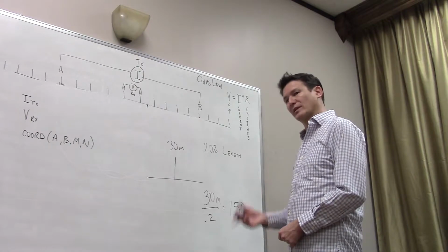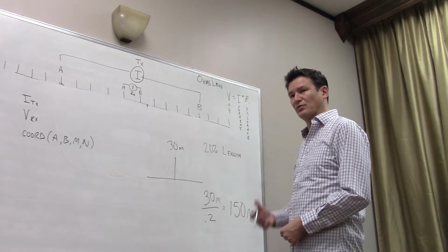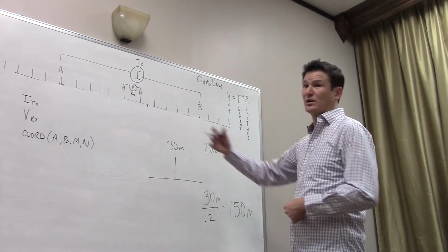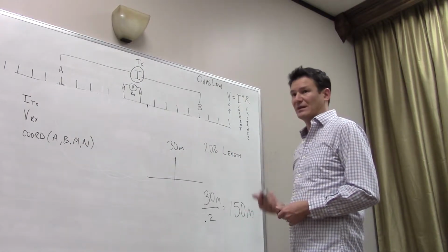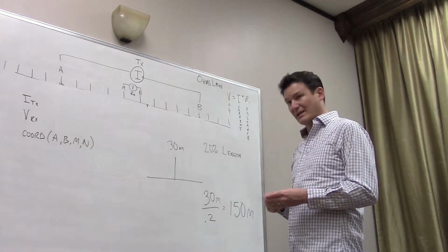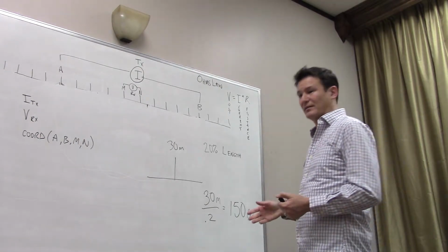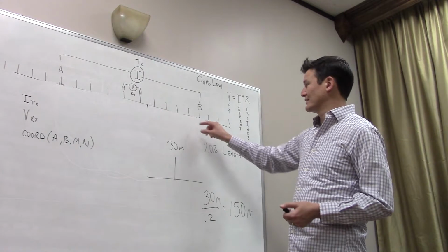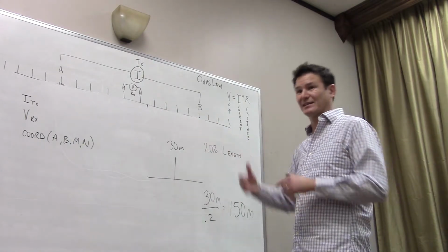Now our systems are 28 electrode, 56, 84, and 112. You could potentially go beyond that, but you're talking about the cost of the systems becoming more and more expensive. And then I have to advise you, at some point, you're really just affecting the resolution near surface rather than at depth.